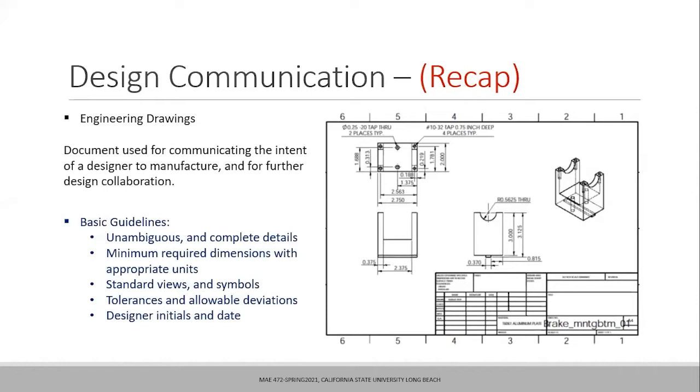So even if your components and your assemblies are going to be 3D printed, you should not have only the CAD model of it. You should also prepare the drawings for it, assuming that you do not have access to a 3D printer and they are getting fabricated as per the traditional machining processes. So you must have the component drawings for your project.